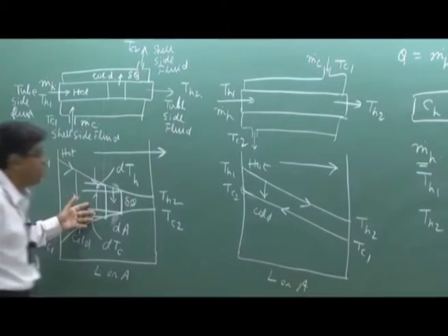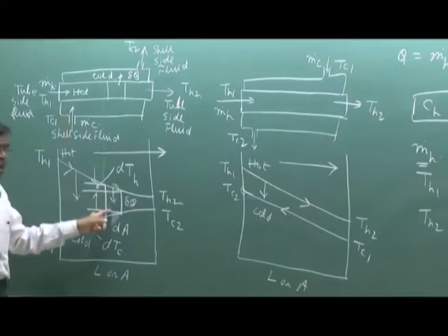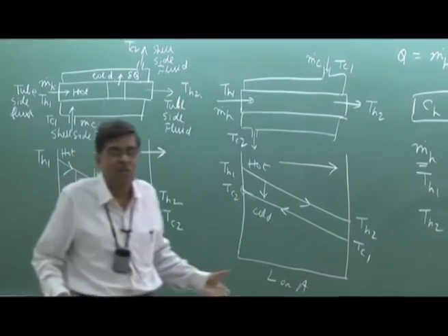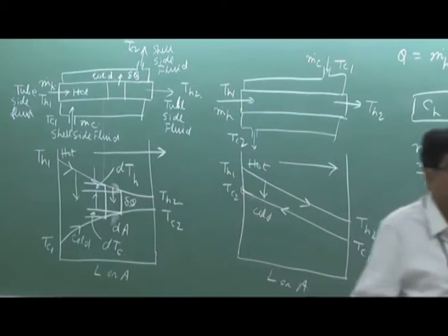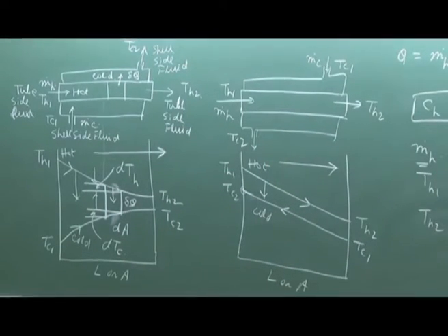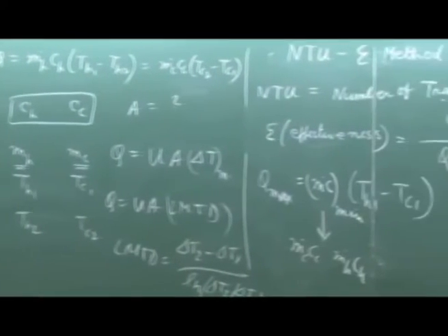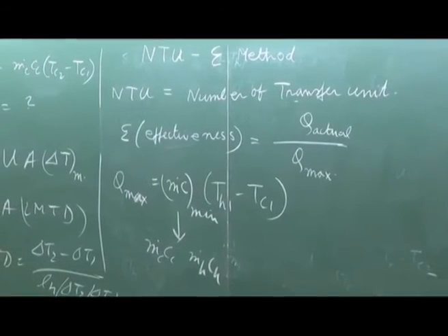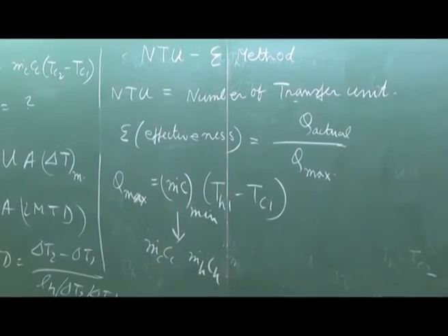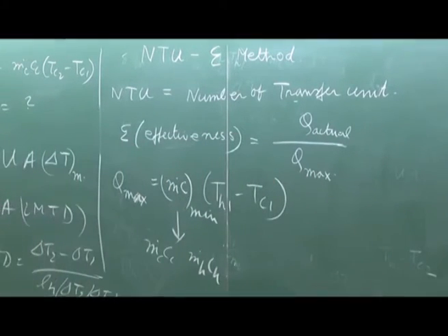But here, even if you give an infinitely long exchanger, it will never reach. Delta S universe can be 0 in an ideal situation of a reversible process, a quasi-static process, but can never become less than 0. It is impossible. So therefore, in a parallel flow heat exchanger, it is never feasible by the physics. So then what happened? This happens like that.